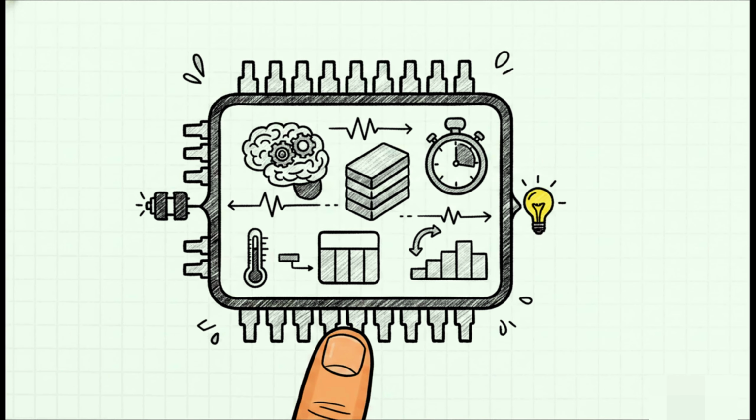Just look at everything packed inside that single microcontroller chip. It's wild. You've got the CPU doing the math, you have RAM for temporary data, and flash memory storing the permanent code, but you also have built-in timers. You've got GPIO pins, that's general-purpose input-output, to turn things like motors and LEDs on and off. You have an analog-to-digital converter, or ADC, which lets the chip read real-world analog signals, like a temperature sensor, and translate them into digital ones and zeros. It even has dedicated communication interfaces built right in. It is an entire, self-contained universe on a chip, no bigger than your fingernail.